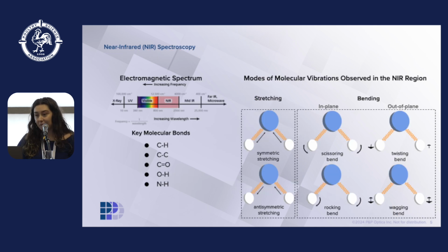The technology used in the applications I'm talking about specifically utilizes near-infrared or NIR spectroscopy, a method that captures and processes information in the NIR region of the electromagnetic spectrum, which is typically between 780 and 2500 nanometers, just beyond the visible spectrum perceivable by humans. Our technology focuses on wavelengths between 900 and 1700 nanometers. The fundamental principle behind NIR spectroscopy lies in the interaction of the NIR light with specific molecules, altering their vibrational modes. This interaction results in characteristic absorption, reflection, and scattering patterns, influenced by molecular bonds, functional groups, and molecular arrangements within the sample. Changes in the vibration of the molecules give rise to overtone and combination bands, predominantly involving carbon, hydrogen, oxygen, and nitrogen, which is great for us because that's what most organic materials are made of.